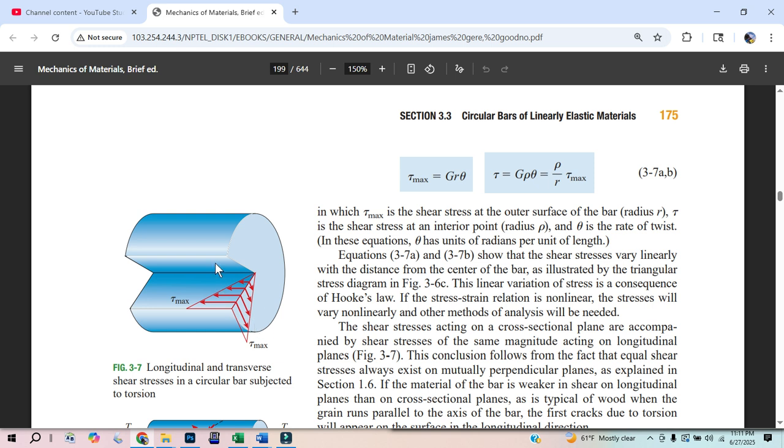So if I had 2 rings of molecules, one ring that was 100 molecules, that's maxed out, and then another ring that's rigidly attached, you know what I mean, because that's what our cylinder is made of, then if I know my stress is 1 on the outer surface, that can provide a torque of 100 pound-inches.